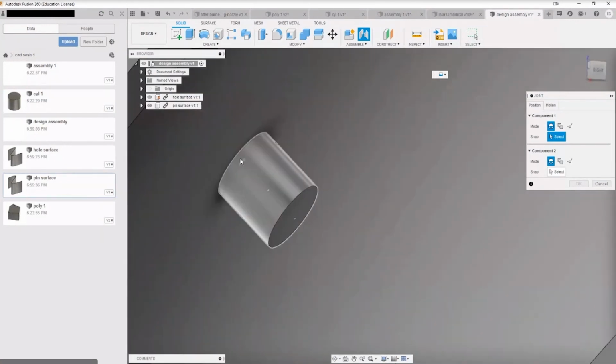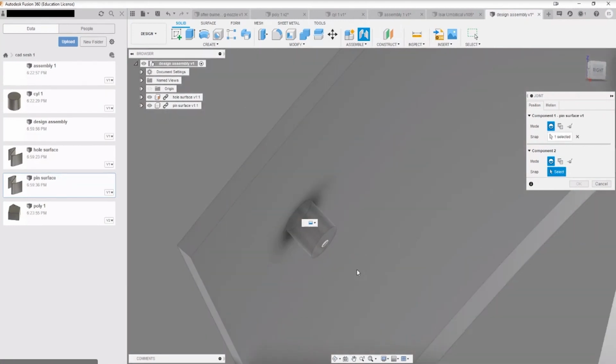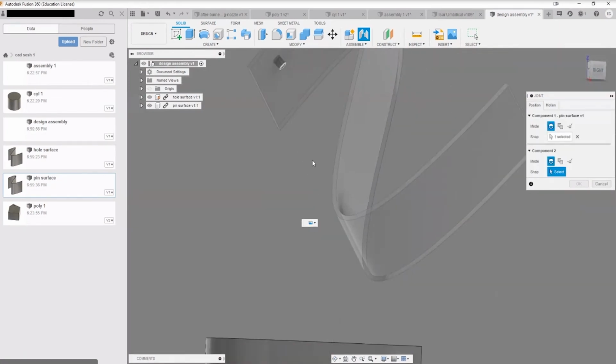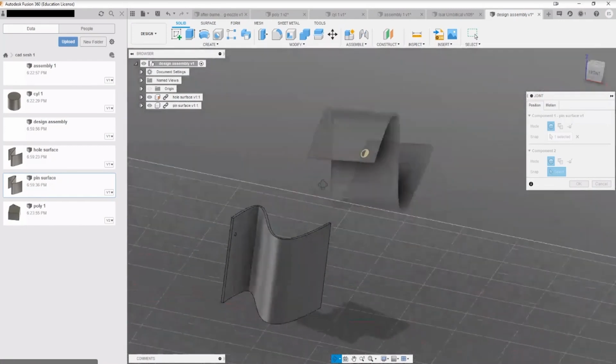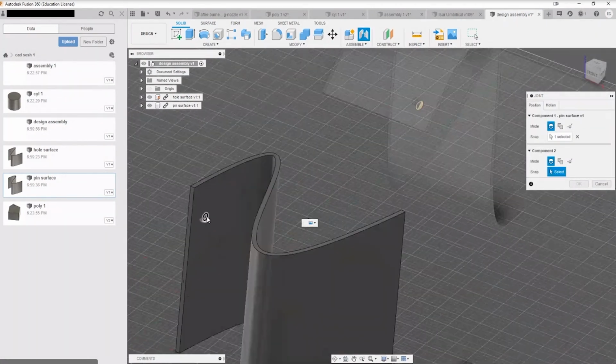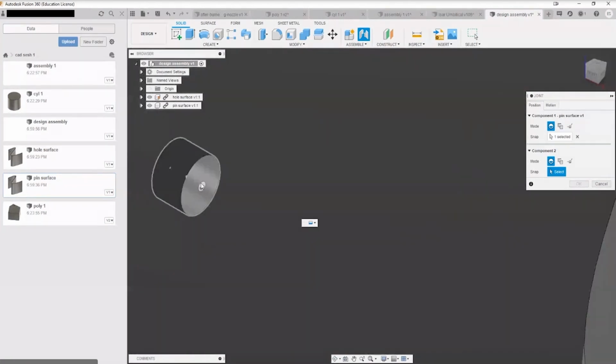Now, I don't know if you can see, but there's 3 different parametric attachment points. So we're going to pick this outer surface one. You can actually pick whichever one, and you'll see literally in a second why. It's not too important, but we're going to pick this outer one. So this is the first component, component 1. We know that's got to attach somewhere around about here. And we know that this outer face, remember, has got to be flush with this surface, yeah? So that's why rather than picking the inside one, you pick the outside one.